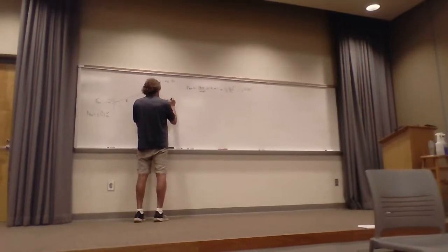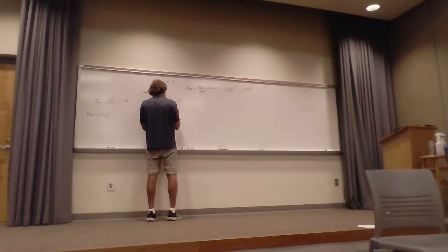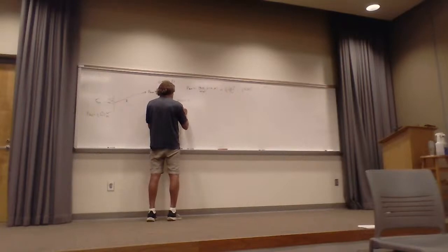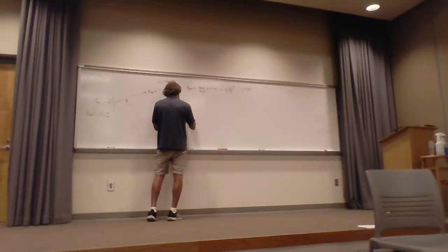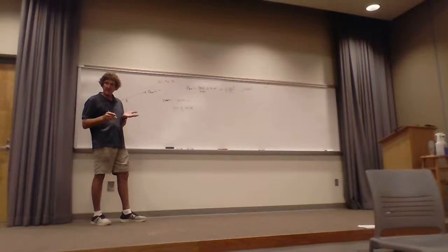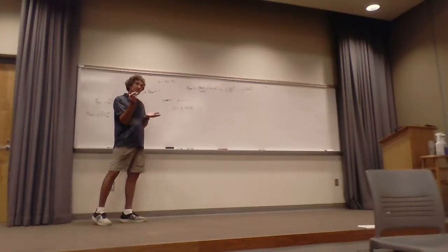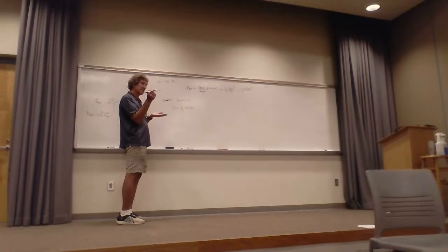For a short dipole, you remember that the directivity was equal to 3/2 times the sine squared of theta, right? It's a peak when theta is 90 degrees or perpendicular to the antenna. You all with me on this? You remember it? That's directivity.